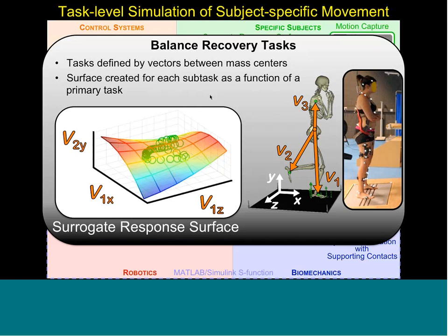And the only thing I would add is that it is so new, finding these relationships between tasks. We've just picked some really big ones here, which you can still see on the screen, between the center of mass and the end effector of the swing foot. But there may be many other tasks, many other relationships between joints and things like that. So to answer BJ's question, it's not published yet because we still don't know what task priority is the right one.